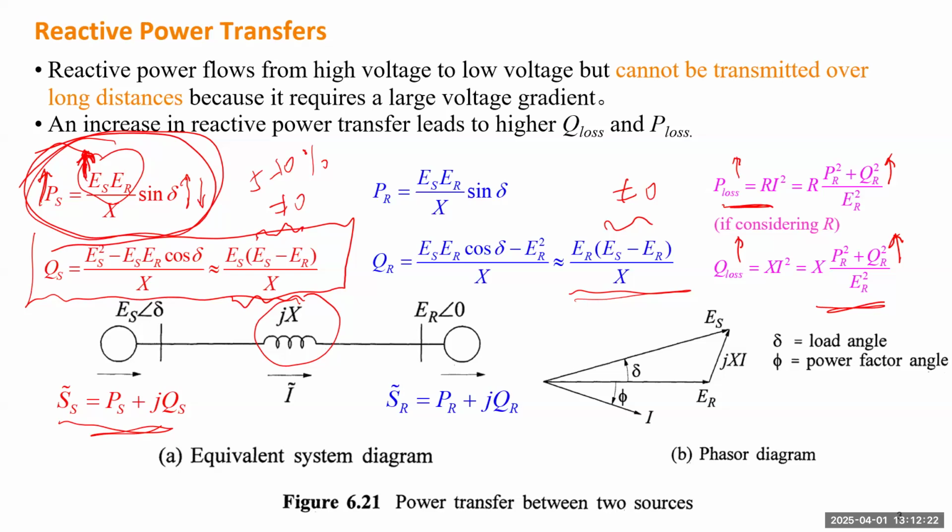That's very critical, because if there's a short circuit near the generator, that will make ER lower. That actually reduces IT power. Think about the power balance between the mechanical power and the electric power. If that power is unbalanced, the rotor will speed up based on Newton's second law.